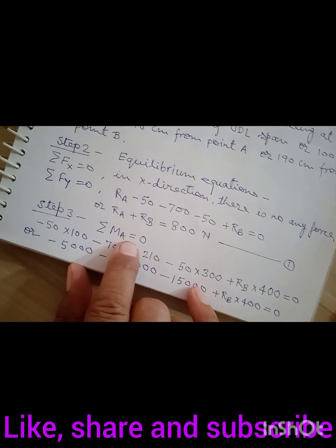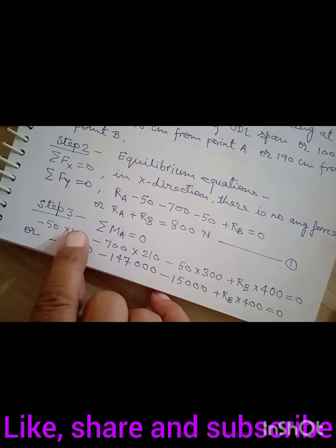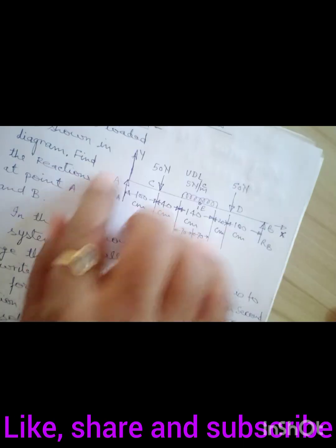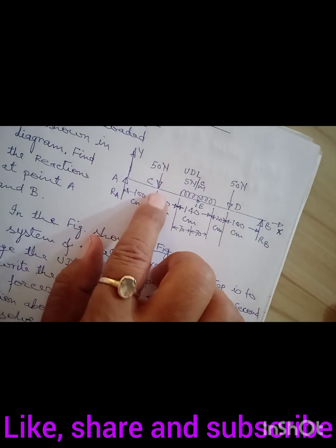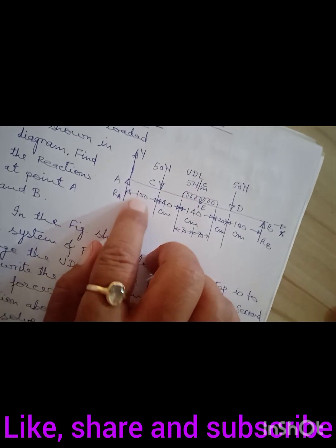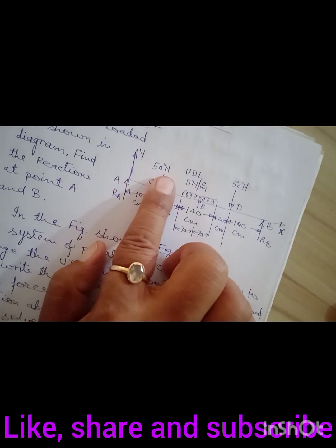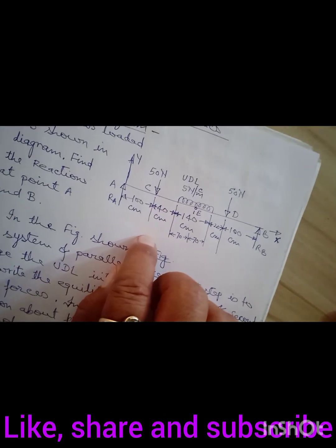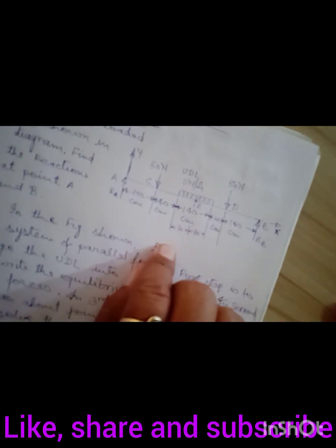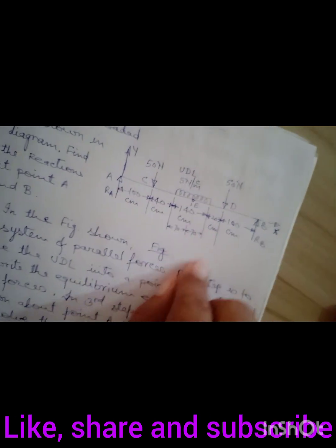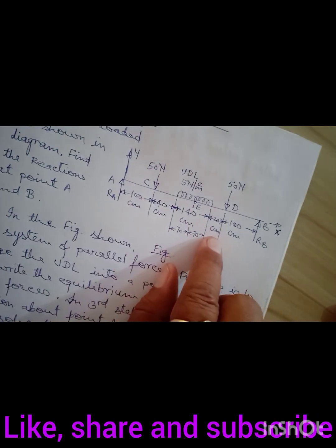In this case we are taking moment about A. Here you can see in the diagram that the 50 Newton will produce a clockwise moment, 50 into 100 centimeter, perpendicular distance 100 centimeter about point A. The clockwise moment is considered negative. The point load 700 Newton will also produce a clockwise moment, and the other 50 Newton will also produce a clockwise moment, so all three are taken as negative.